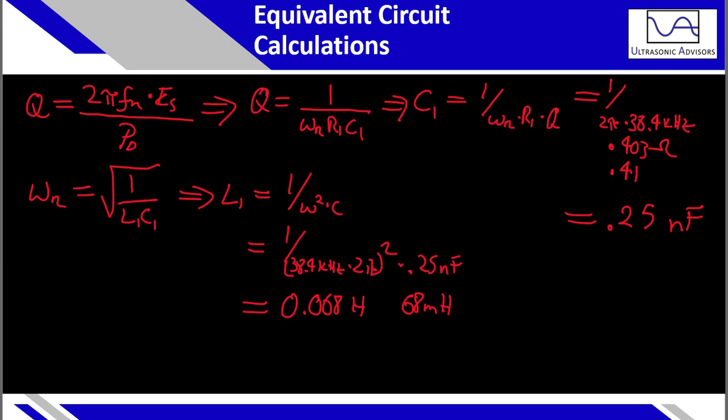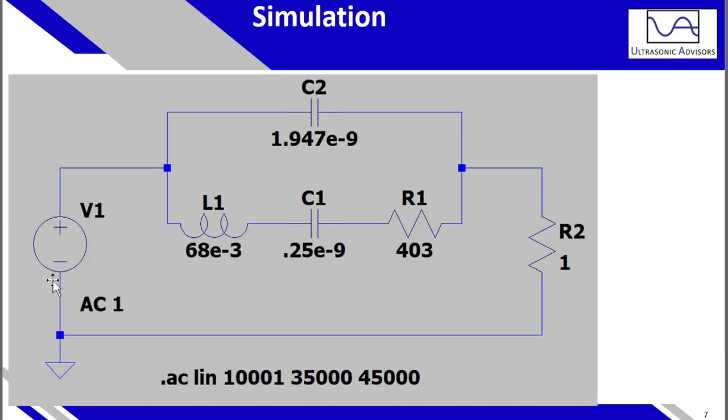But after we calculated all of the equivalent circuit components, I drew this up in a program called LTspice. It's a very simple circuit simulation program, extremely popular. And we see the capacitance, the static capacitance, and also our LCR circuit all represented here.